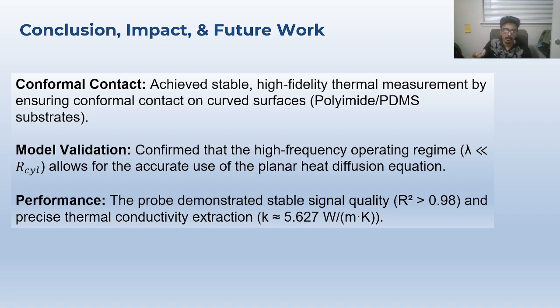And in terms of performance, the probe demonstrated stable signal quality where R squared was greater than 0.98, and precise thermal conductivity extraction, which we got to be around 5.627 watt per meter Kelvin.